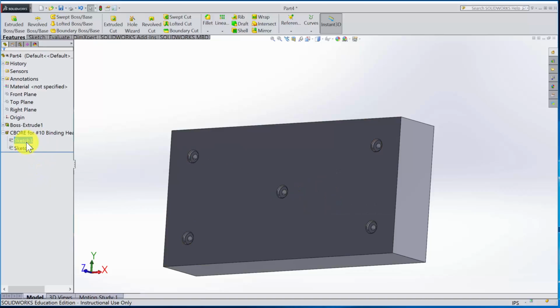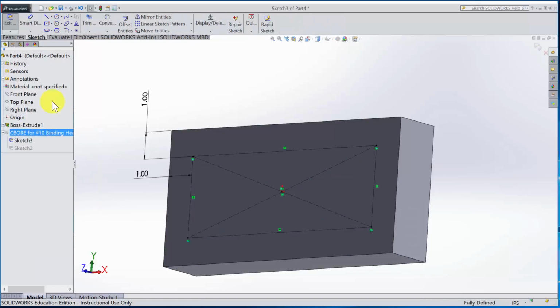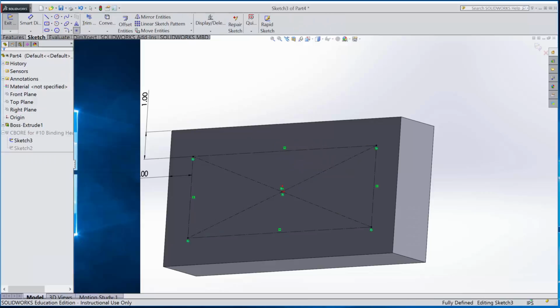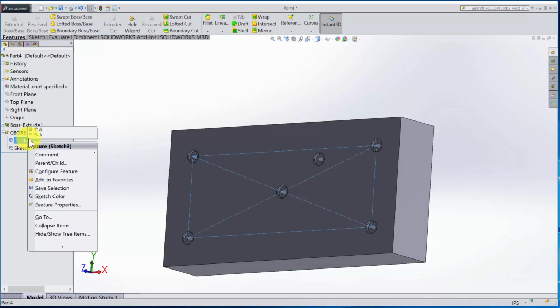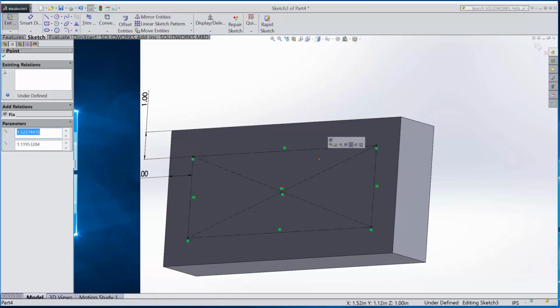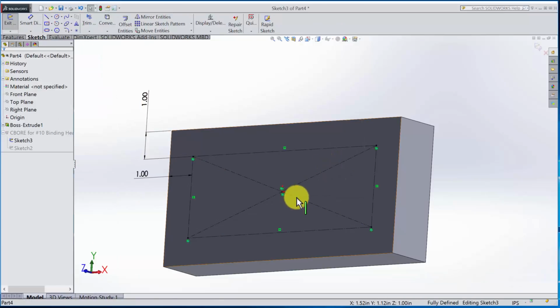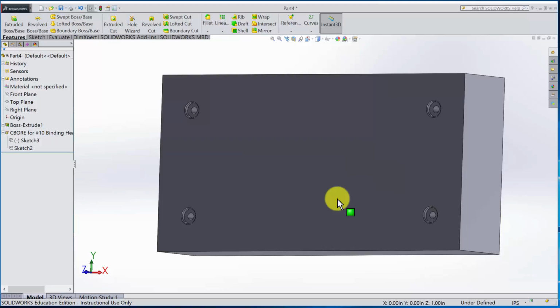So this is another important point in this sketch 3. When I'm editing the sketch, any points that I drop in here, when I exit the sketch, will be viewed as another hole. So it's easy to add new holes within that sketch without having to go back into the whole wizard. So let's edit that sketch again. I'm going to delete this point. So by deleting that inner circle, that inner point, I've removed the hole from that location, but I also now have allowed my sketch to not be fully constrained.